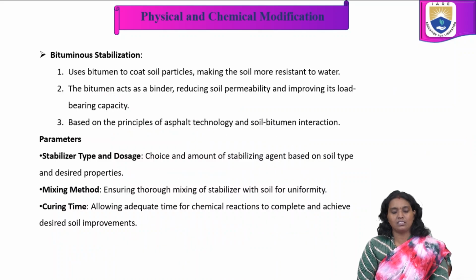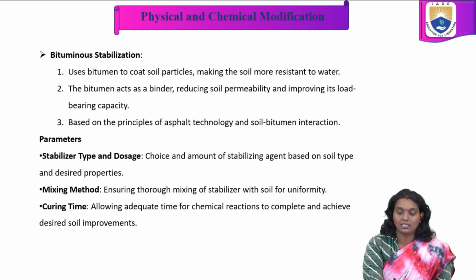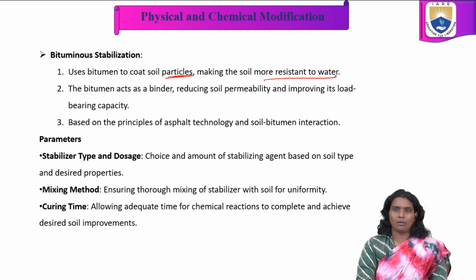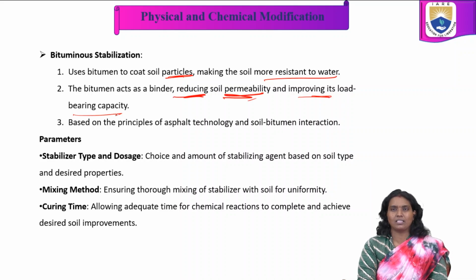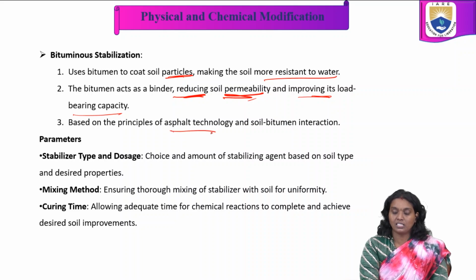Coming to the bitumen stabilization, it uses bitumen to coat soil particles, making the soil more resistant to water. The bitumen acts as a binder, reducing soil permeability and improving its load bearing capacity. It is based on the principles of asphalt technology and soil bitumen interaction.